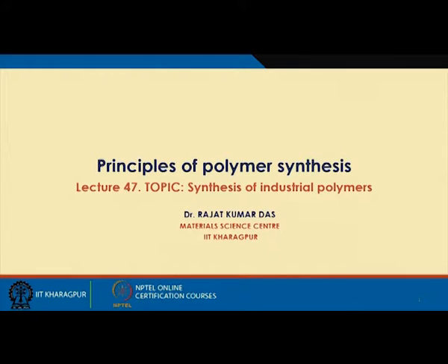Welcome back. We have been talking about the structure property relationship of bisphenol A polycarbonates, mainly how to preserve the impact strength while we try to increase the thermal stability of the material, in other words, while we try to increase the glass transition temperature of the material. So, just a quick recap.